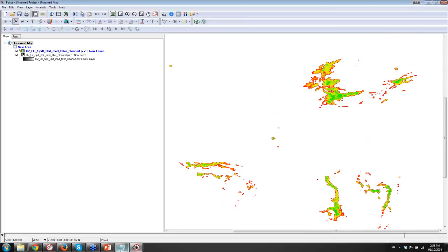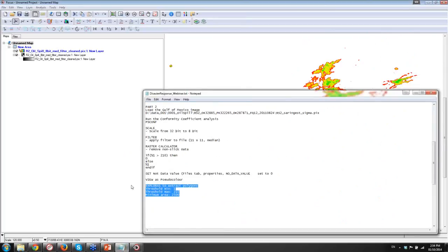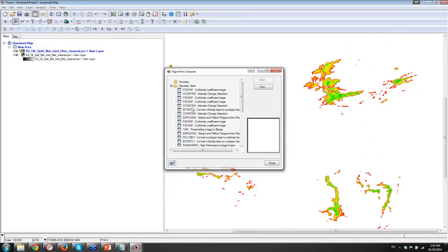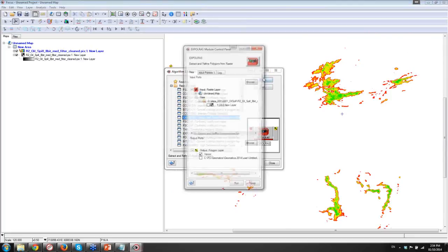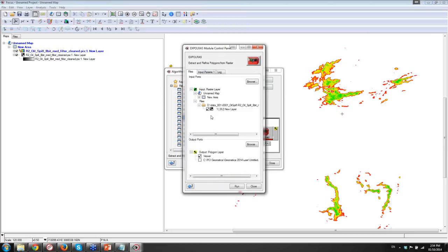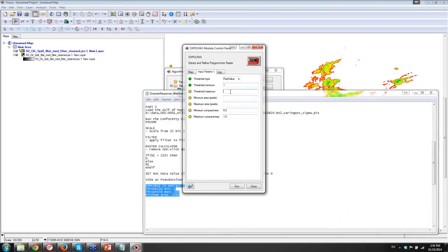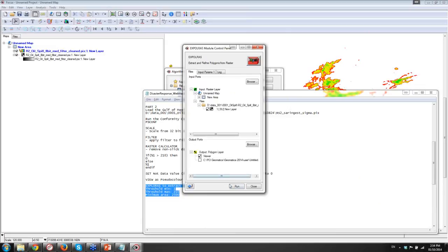And the final step to get to our product is we can run another algorithm, and this one is known as our extract polygon algorithm. It's called XPolRAS, and I can select my layer and select my values. So I'm going to use 1, so the pixel values have to be at least 1, not zeros, and I can set my threshold at 210. So in this case, I'm trying to keep the values that are representing oil, these oil slicks, and then I can search a number of pixels, so I'll run 2500, and I'll run that to show that in the viewer.